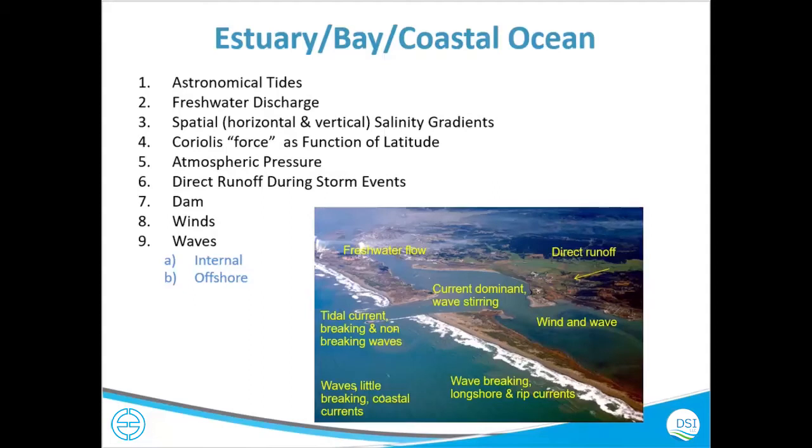There can be groundwater recharge somewhere. Groundwater is usually represented on the bottom cell because it's coming from the bottom, and then you can assign the flux, or you can assign the discharge in cubic meters per second. There is an option in EFDC Explorer that can help you decide which one you want to choose when you're representing the groundwater in your model. So in these kinds of situations, the Coriolis might be important because it's a little bit bigger domain.